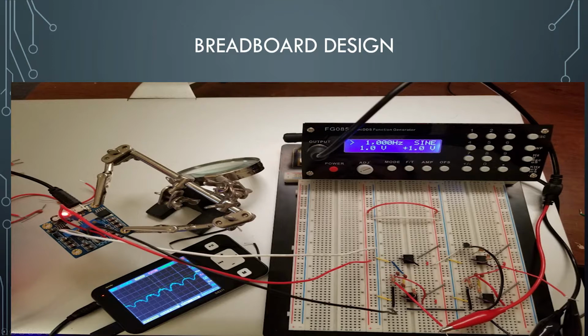So what we have here is our constructed circuit. We have worked with four UA741 operational amplifiers connected to a plus 12 and minus 12 volt power supply. As for the AC power supply, we have an RMS value of 0.707 volts with a frequency of 1 kilohertz.